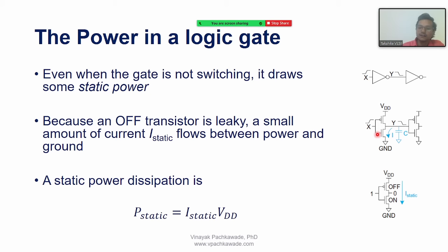Why is it leaky? So you see here now, because of the scaling, there are many adverse effects. They are called scaling effects. So you have this metal oxide semiconductor: this is SiO2, and this is your metal or polysilicon. So basically you have this MOS capacitor right over here. This is your metal, this is SiO2, and this is silicon.